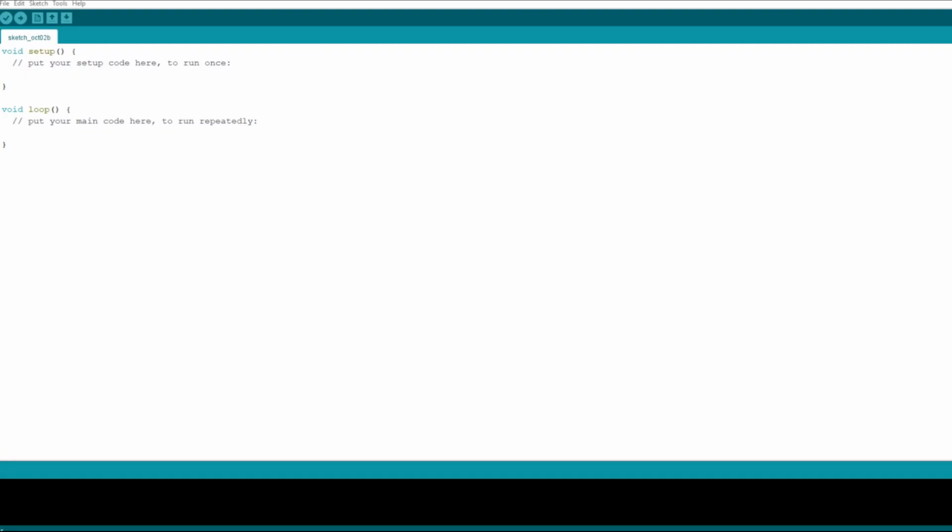Yes, my dear friend, in this lesson we will learn about the interface of Arduino IDE. First of all, as you can see here, there is the void setup part. The codes of the Arduino board are written in C or C++. The structure that starts with void here is a function. The void setup section allows us to set up our Arduino codes. And here the codes run once. And the void loop part you see here is our function that repeats the given commands continuously.